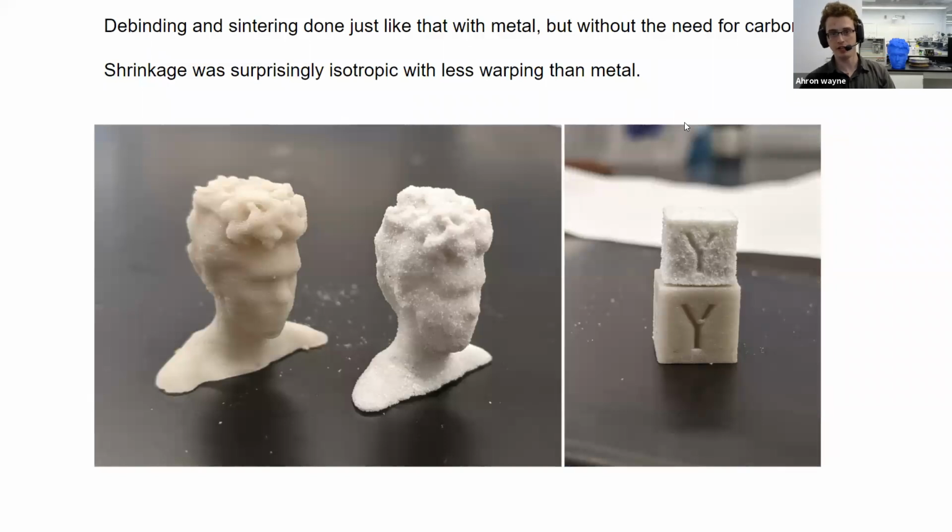And then debinding and sintering is just like that with metal, but it's a lot easier because you don't have to worry about oxidation. Glass is already an oxide, ceramics are too. And I was quite surprised to see that actually they sinter really well. They debind and sinter, and you get this nice pure looking substance that holds its shape very well. It probably shrinks more isotropically than with metals so far for me, which lends it to the idea that part of the reason for that is because of the presence of oxygen. So nice shrink.